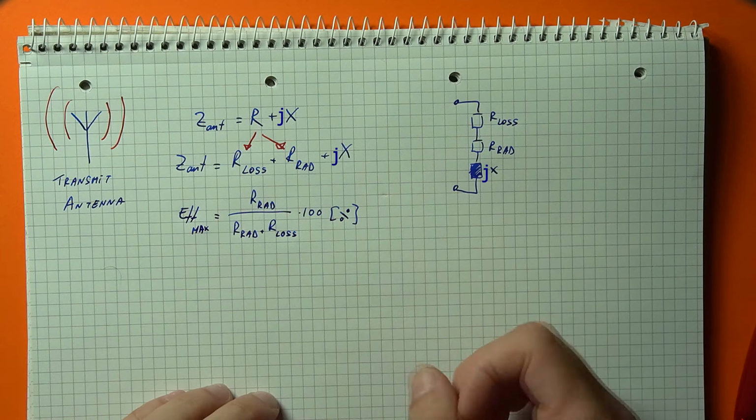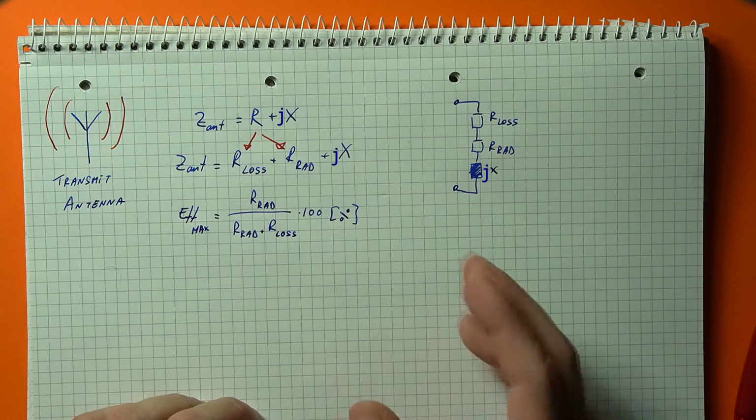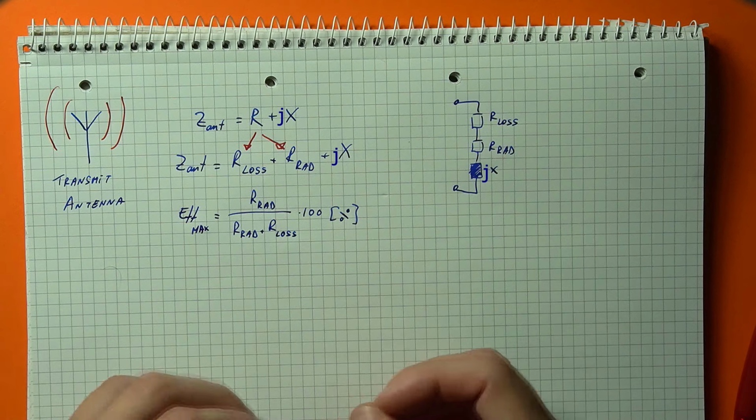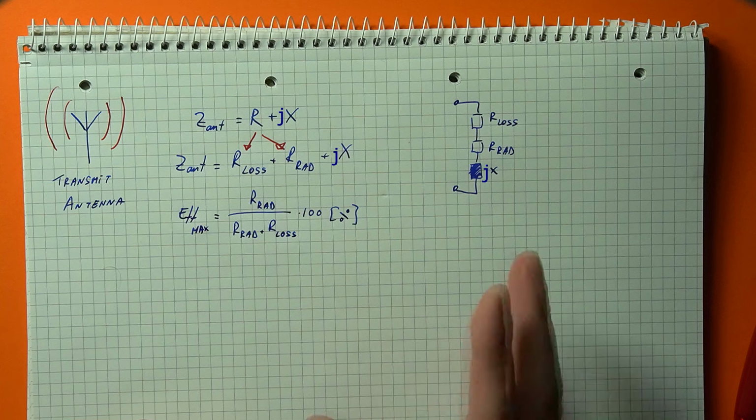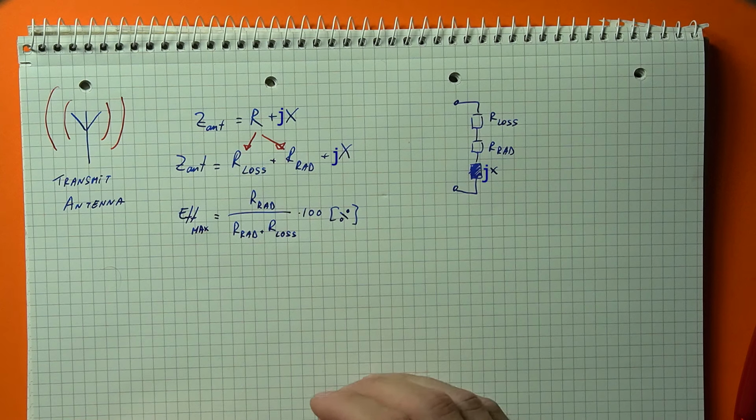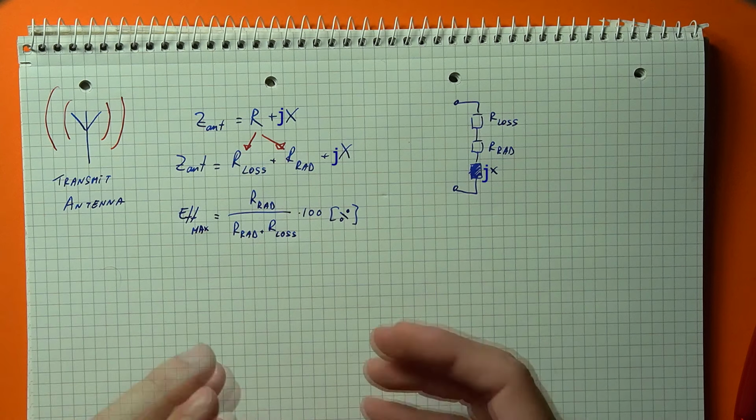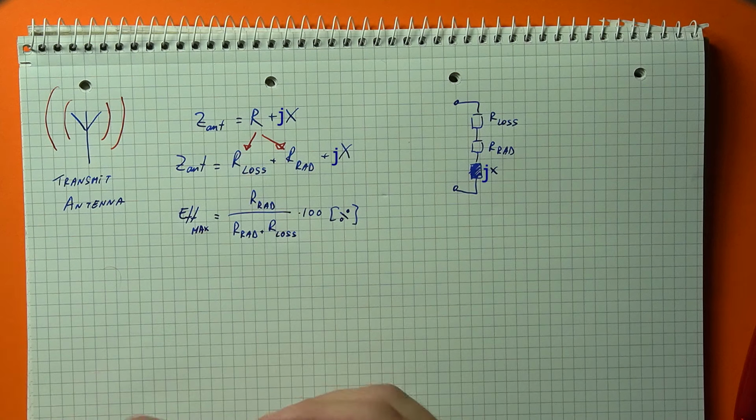Finally, the reactive bit can have an ideal value of 0 under special cases, like a half-wave dipole or a quarter-wave monopole, but in every other case, you will get some reactive element, either capacitive or inductive, based on the antenna geometry and the test frequency.